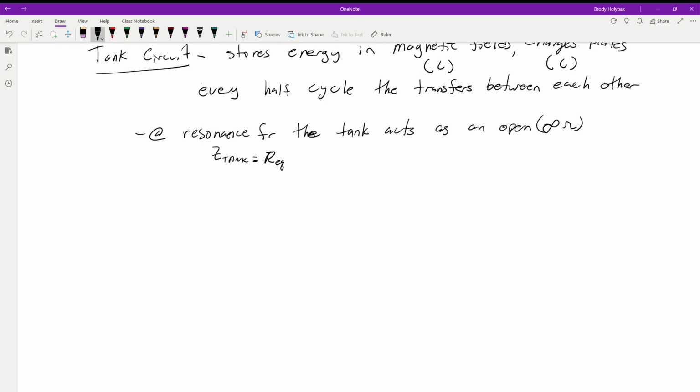We're looking at 1, 2, 3 degrees maybe, with just the residuals when we actually go to calculate the LEQ and all that. But what we have here is very, very little phase angle, so we should be seeing a 0 phase angle on everything coming out, with the currents and the voltages and things like that. And then we should also see a little bit of a drop between the resistor we have coming in and the source. So it's something to be aware of.